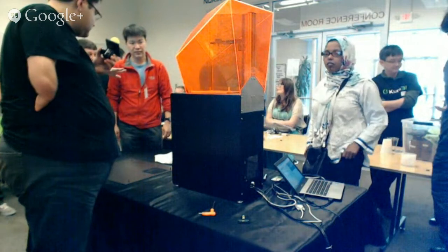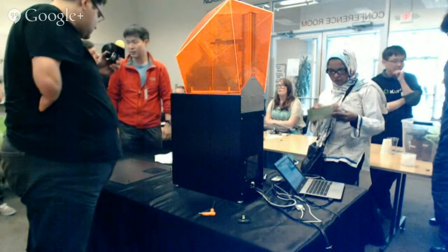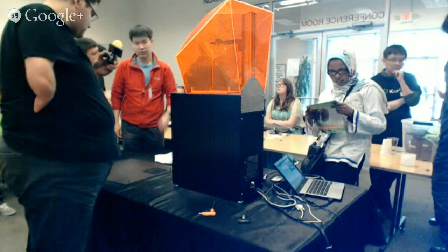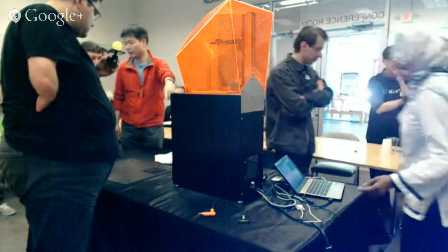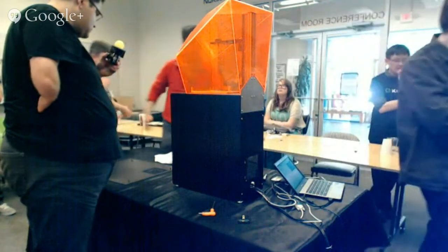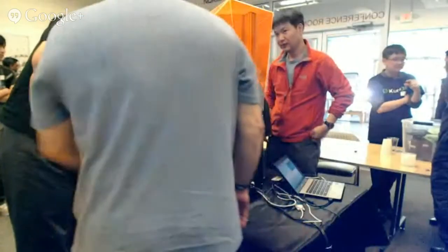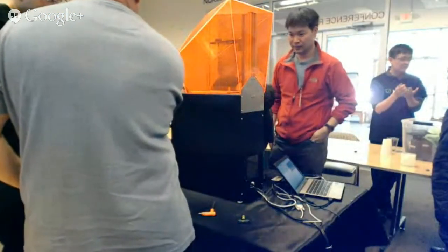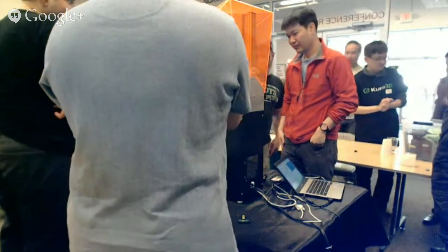You're less likely to exceed the interlayer adhesion, but you might break something. So I tried to print this whole thing on one post. It's not an issue of interlayer adhesion. It's just not strong enough. It's going to break off. If I try to print a pyramid upside down, that's not going to be very good, because only the tiny tip is going to be sticking to the bed.